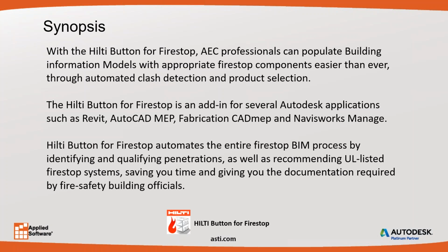The HILTI button for Firestop is an add-in for several Autodesk applications such as Revit, AutoCAD MEP, FabCAD MEP, and Navisworks Manage. This button for Firestop made by HILTI automates the entire Firestop BIM process by identifying and qualifying penetrations as well as recommending UL-listed Firestop systems, saving you time and giving you the documentation required by fire safety building officials.